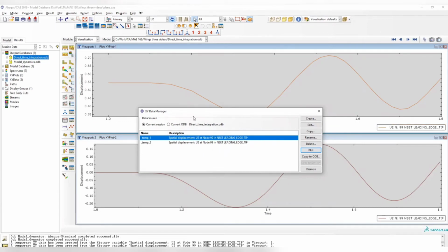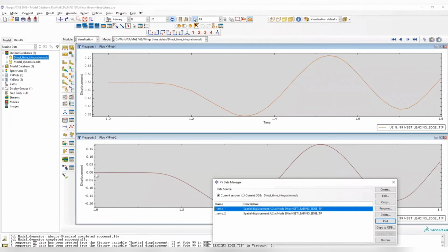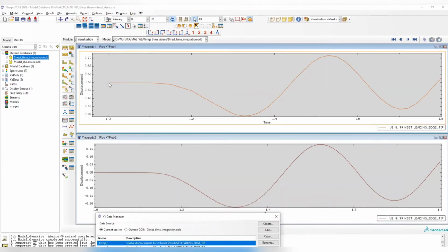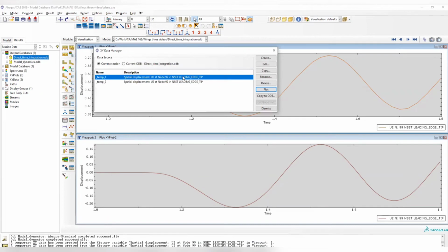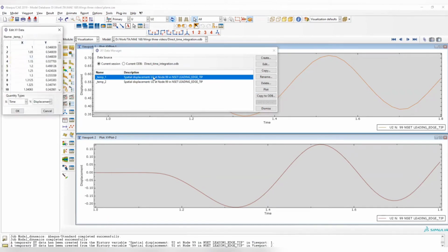And another thing you can see that is different is the initial value. As I said, model dynamics is an add-on to the base state, so it won't show the base state here. So although you have an initial value of 0.55 or something, it won't show in the model dynamics. So to fully compare these two, you need to add the initial state to the result. To do that, let's open the first one and copy the first two columns here.